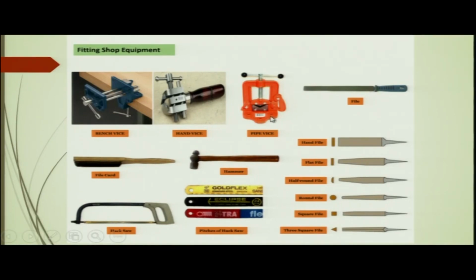This is the housing of the vise. This is the fixed bed, and this is movable. Okay, this is movable. This is rigidly attached at the end of this lead screw. On the other end, the lead screw has a handle. Using this handle you can rotate the lead screw. Here inside this is a threaded hole. Through the threaded hole this lead screw is rotated, and this will go up and down.